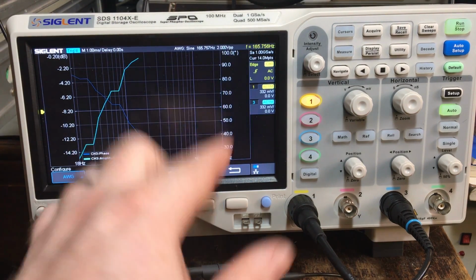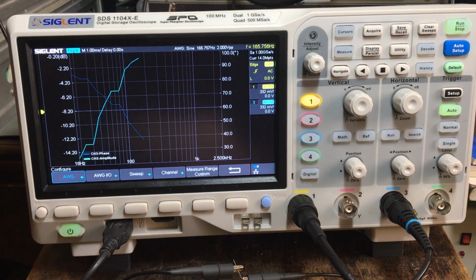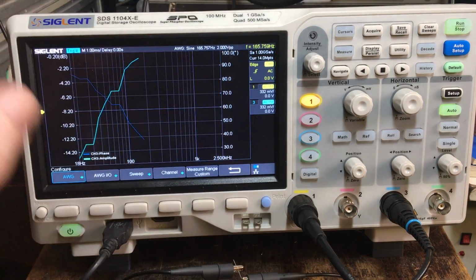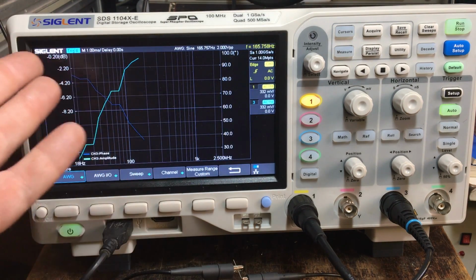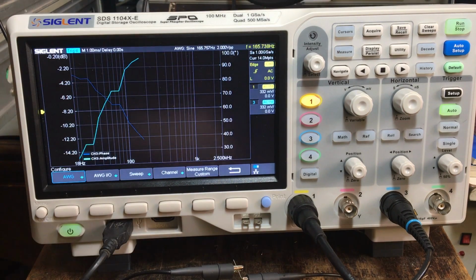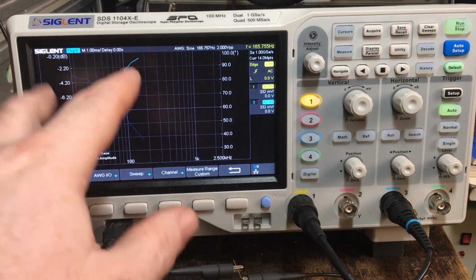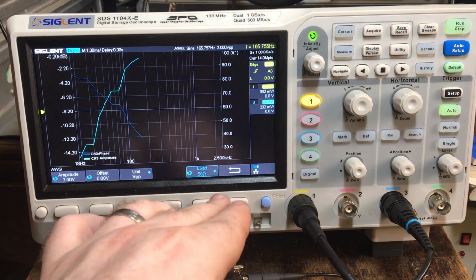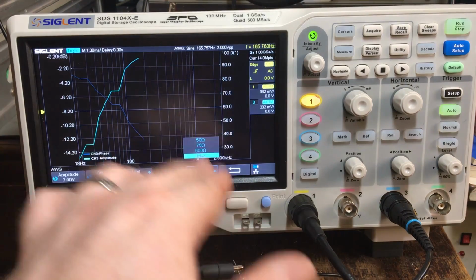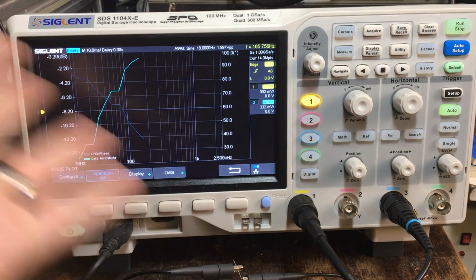But if you've got a custom measurement range, that would allow you to set these levels and things like that to allow for that mismatch. Okay, because unless it's a 50 ohm system and you've got it set to 50 ohms, you're going to get that error message come up. It still works, but it gives you that error message. But if you've got a high Z input, then you just simply change it anyway. It's not a problem. I think it might change some calculations. So we'll go back over here, put it back to high Z, and that'll be fine without a load. I can do that now with no load on, and that'll be absolutely fine.